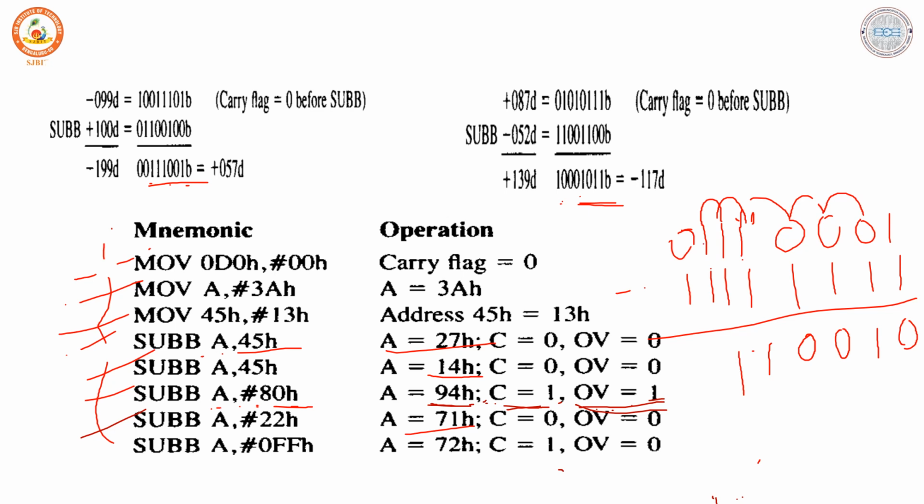Okay, now there is a requirement of a borrow from the seventh nibble. So in that situation what happens, 0 1, I have to ask for a borrow, right, from the C bit? So what happens now, C is set to 1, okay, borrow will be set to 1, then this is going to transfer 2 minus 1, it is 1, and now here 1 is there, now 1 minus 1 will be set to 0, because this fellow is going to give 2, right?